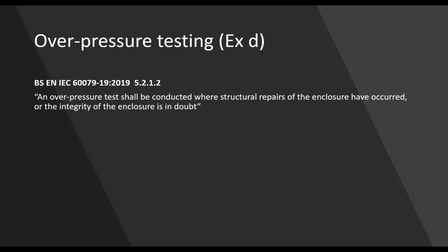There's mention of overpressure testing. There was a guy going around the world from Australia who I think had shares in pressure testing equipment, saying that whenever an EXD piece of equipment was dismantled, you should perform a pressure test. No, you don't. The standard says an overpressure test shall be conducted when structural repairs of the enclosure have occurred or the integrity of the enclosure is in doubt. That is the only time you need to perform a pressure test. And remember, the pressure test is only for EXD because you are seeing if the enclosure can still contain an explosion.